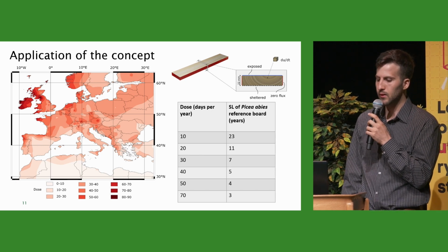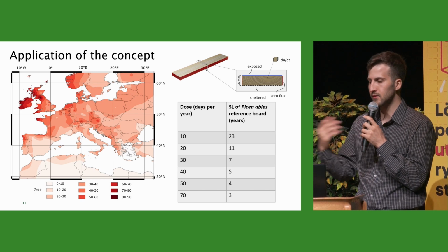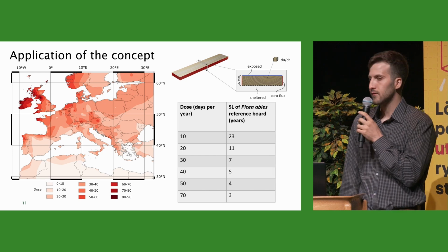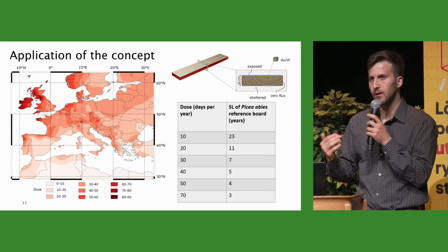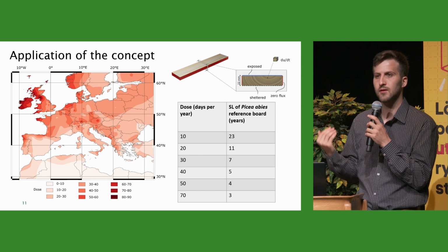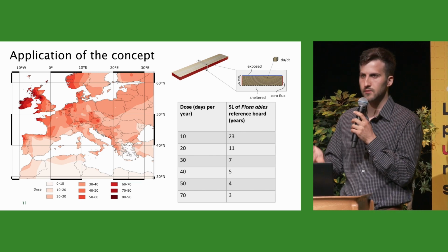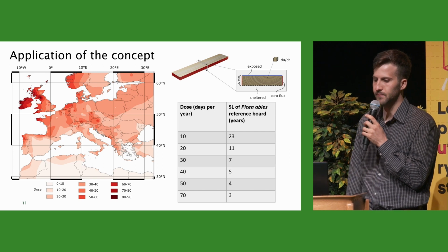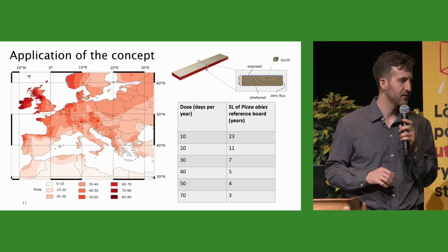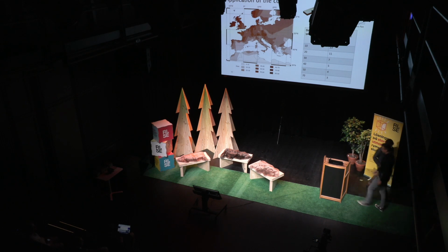If you want to then change your design so that you can have a service life of what the building standards dictate, then you would have to change the durability rating of the material. So you can use either a treatment or modification or just a naturally more durable timber species. And Jonas will also show you some things on the influence of joints, etc. So that's all from me. I went a little bit over, but I think that's fine. Thanks, Jonas. Thank you, Philip.